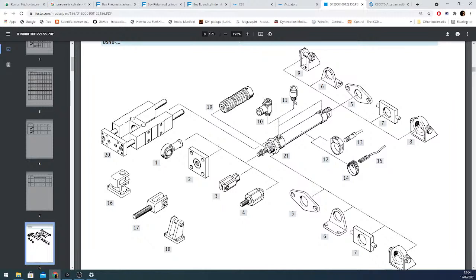We have options for the cylinder. How do we want to connect the compressed air to the cylinder? Do we just use a coupler that screws right onto the cylinder, or we are using a coupler that has a flow restriction here, the flow control valve built into it? Do we need some clamps for the sensors? So maybe we are using magnetic sensors for positioning.